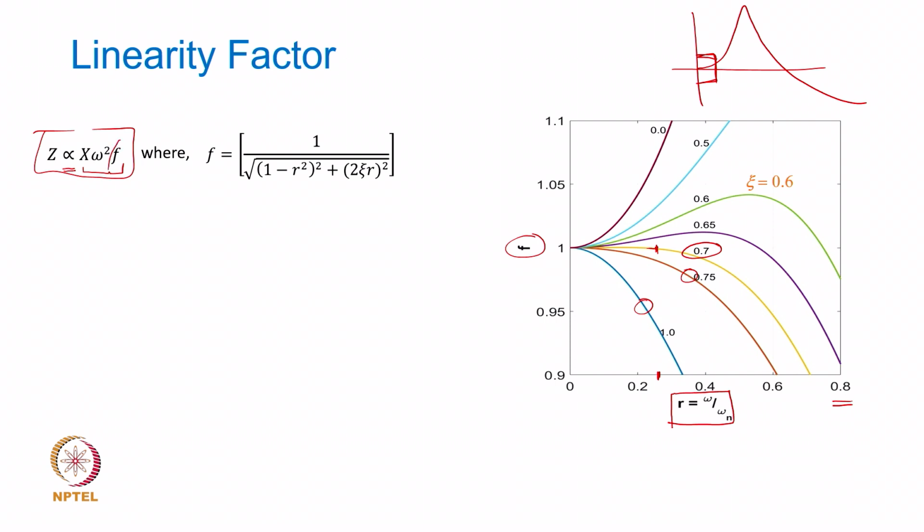If f is equal to 1 for a certain frequency range, now I am talking about this frequency range 0 to 0.25, this f is going to be 1, and then you can always say that whatever the charge output that you are getting from an accelerometer is going to be proportional to the acceleration, right, directly proportional, and without any multiple. Of course, there will be omega n square that has to be accounted for, but that is not going to change the behavior as such.